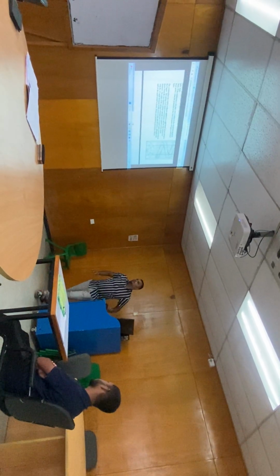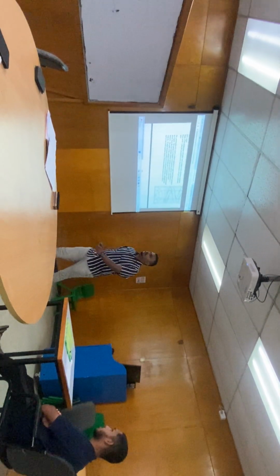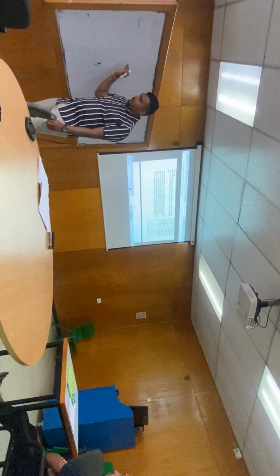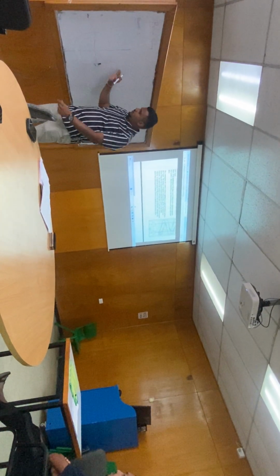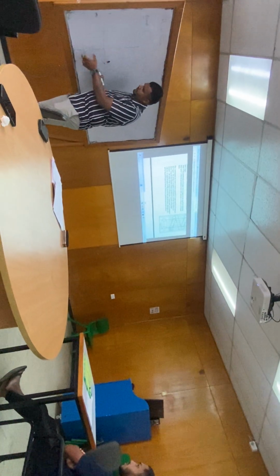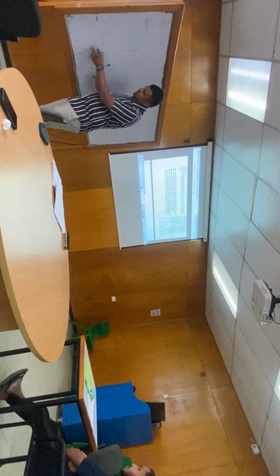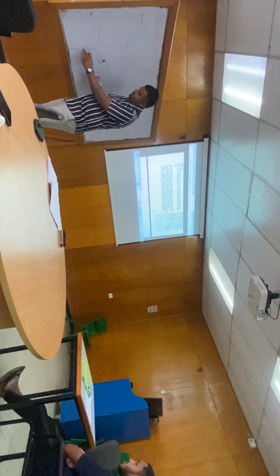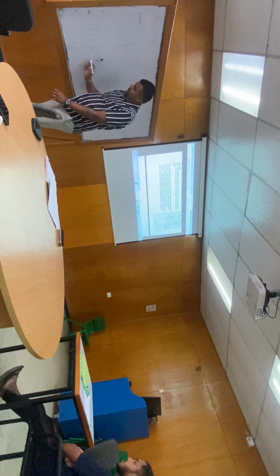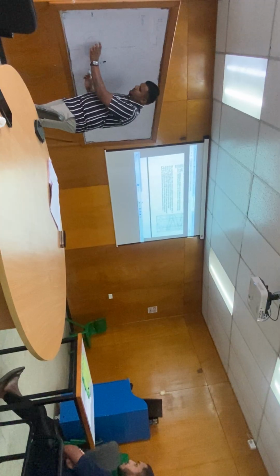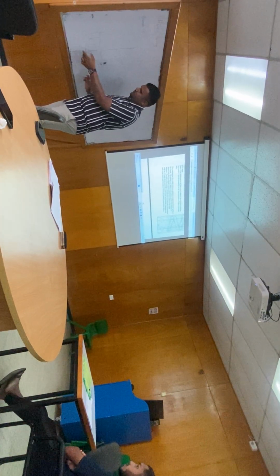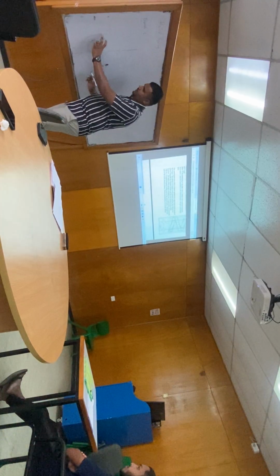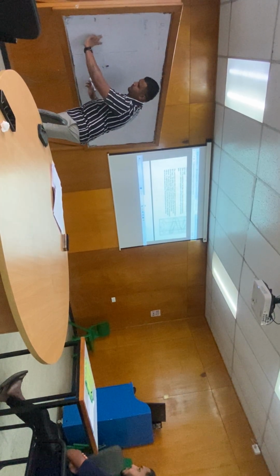So I have drawn one example over here. First, what you will do? You will divide the circle into 12 equal parts. So put your compass over here and mark. Then on the bigger circle, put it over here, mark.